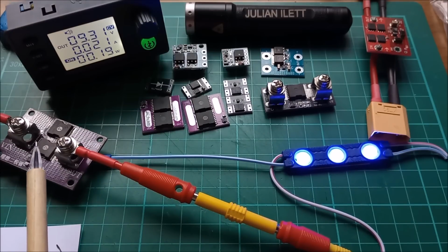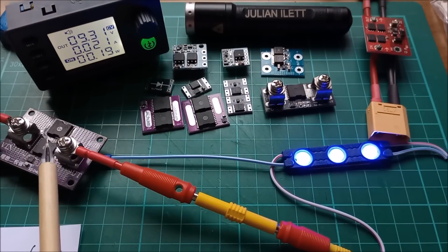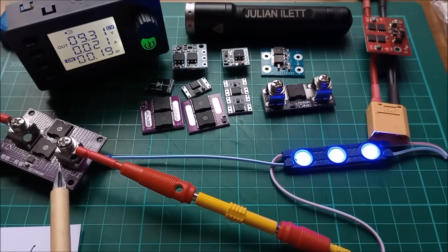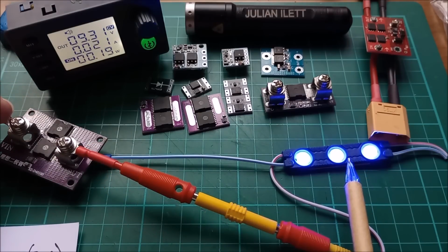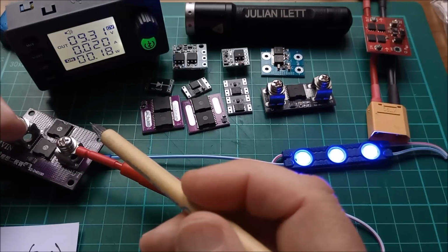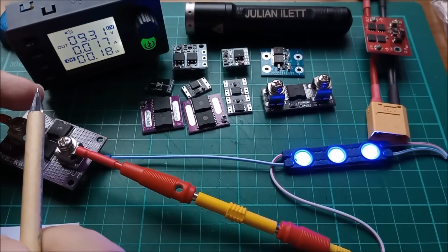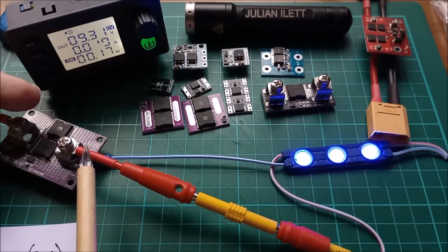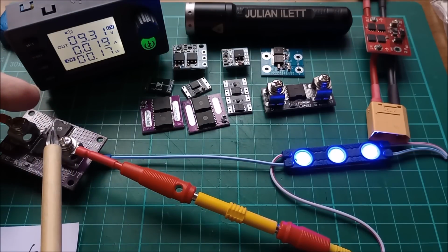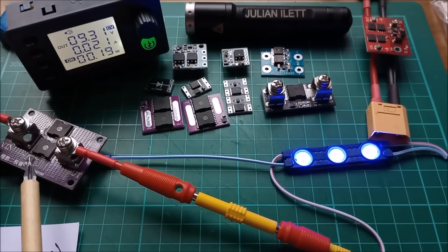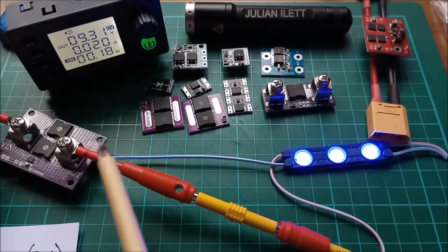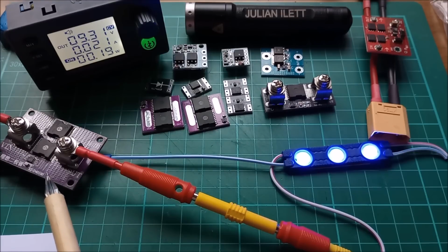But this just shows that the only way that this chip can operate with no ground reference is that it has to take its power from the fact that during this very brief off time, there is a 0.6 volt, well, it's this way around, isn't it? 0.6 volt higher on the input than on the output, and that 0.6 is lost across these body diodes. The chip uses that voltage to pump up this capacitor. I think it goes between 6.3 volts at the top and 5 point something at the bottom. I'll just check that on the datasheet.